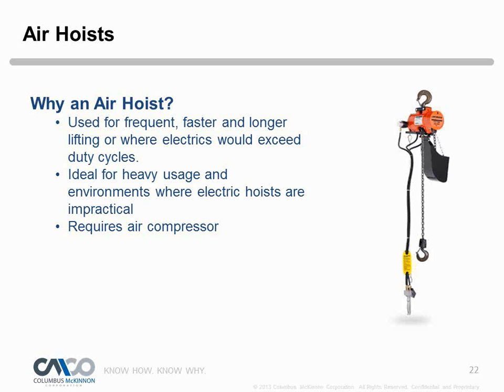We do offer spark-resistant features in the wire rope and the electric hoist, but in this case it's even better, one step further, where you're going with an air system, so you're eliminating that electrical spark altogether. And so in that case, it's more practical to use an air hoist. But you do require additional equipment. You need to have a compressor to supply that air hoist, the proper size compressor and equipment to make those air hoists run efficiently. Right. Okay. Thanks. Very good question, though. Thank you.